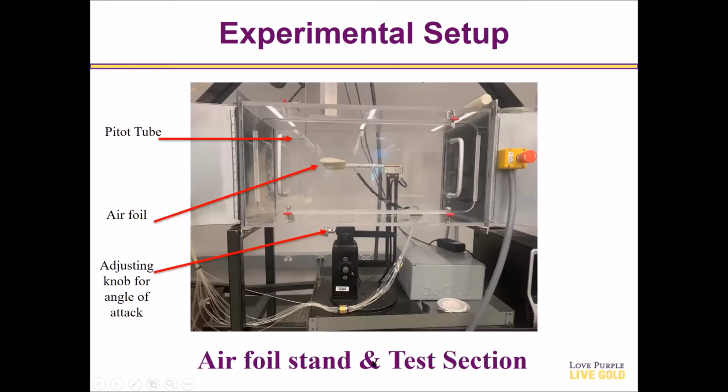At first, we will discuss the airfoil stand and test section. Here we can see the pitot tube. The pitot tube position can be controlled using a motorized system through a LabVIEW interface. However, considering the airflow pattern and to avoid any flow discrepancies, it is recommended to position the pitot tube 12 inches above the bottom surface.